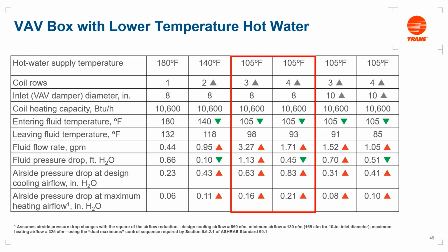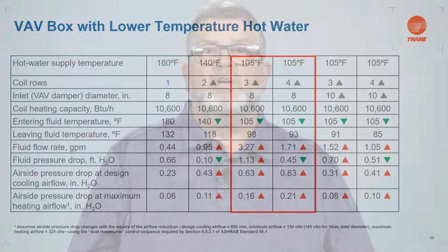However, in some cases, upsizing the VAV box inlet diameter may require using a higher minimum airflow setting to ensure proper control at lower airflows. It is recommended that the dual max VAV control sequence be implemented to allow for less hot supply air temperatures when heating is required. Another strategy for electrification is to use fan-powered VAV boxes.